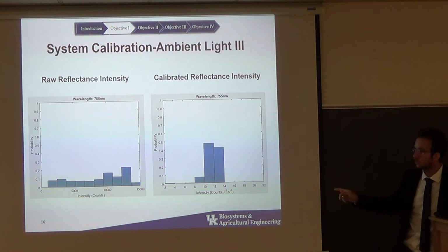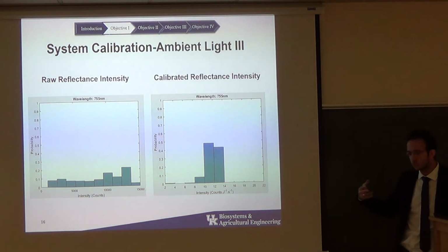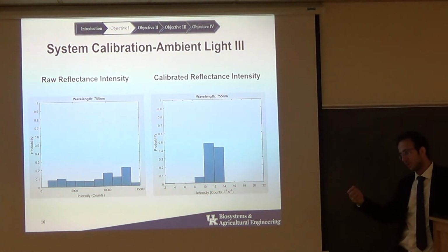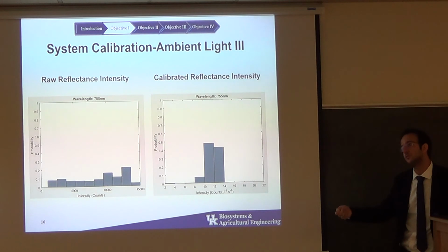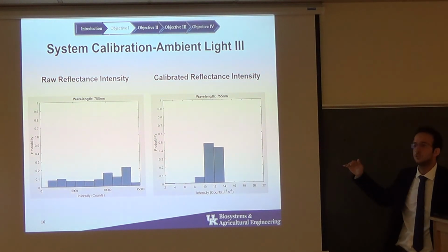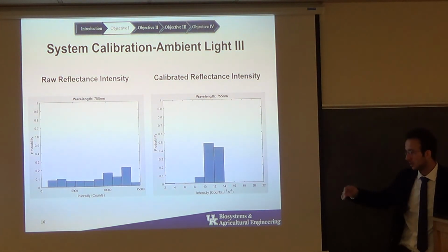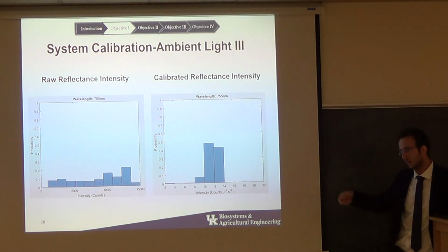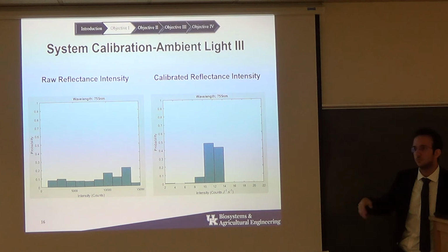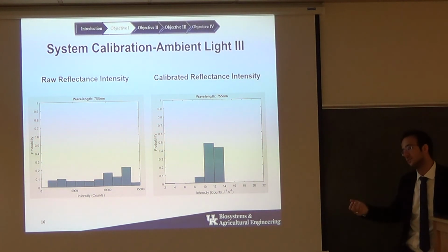For the type of algorithm we are using, it's a closed loop system. Every time we take a measurement, we read the output and see how close we are to the desired integration time or a desired profile. We change it for the next input, and we apply it to the input again. So we are changing it again and again.